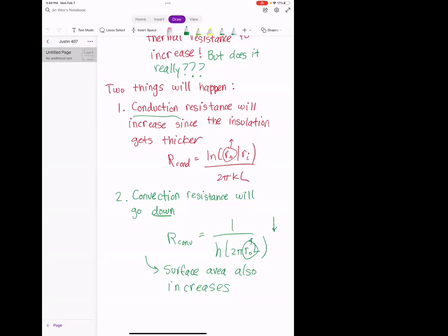The one we did in the lecture was a special case, an insulated surface. When you have an insulated surface, you set the entire thing equal to 0. But here we don't have an insulated surface. What we have is a surface being heated by a heater, so instead of equal to 0, you set it equal to whatever the heating rate is. Let me look at this again. Yeah, go ahead.